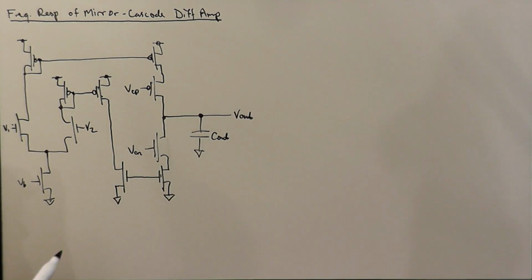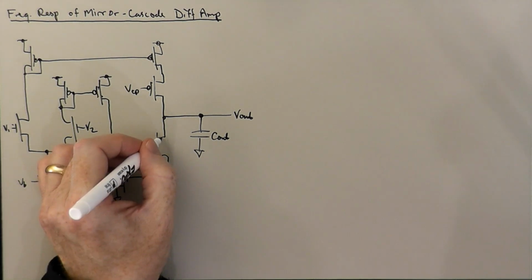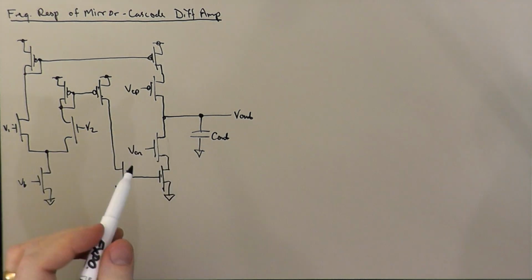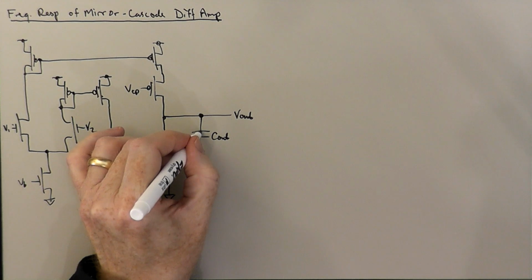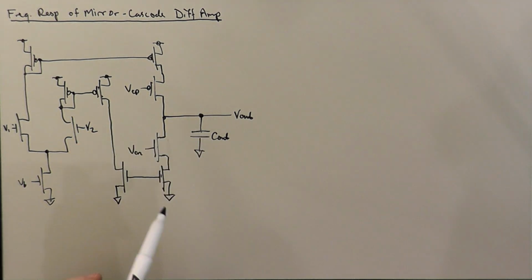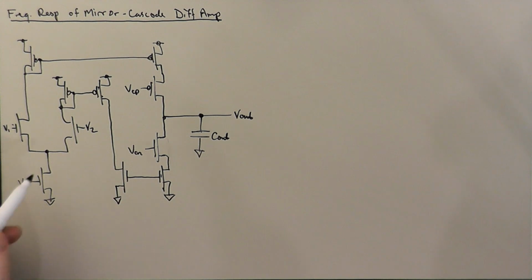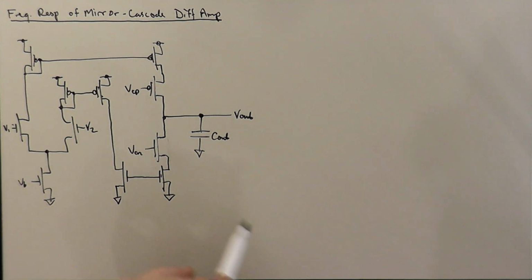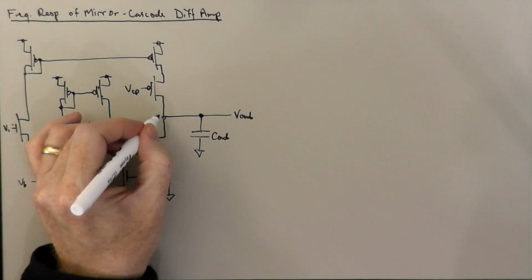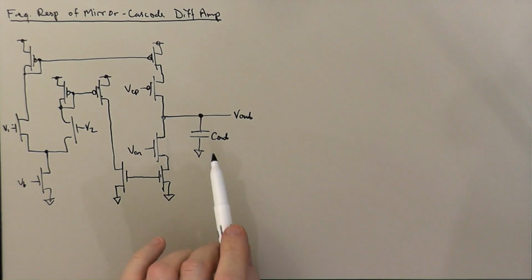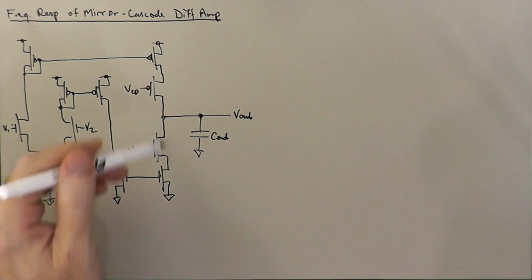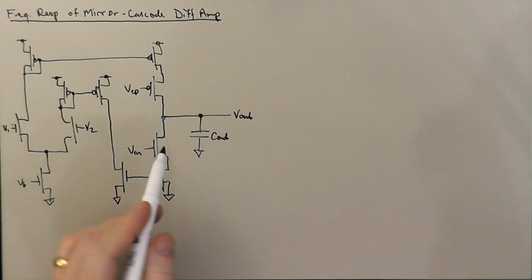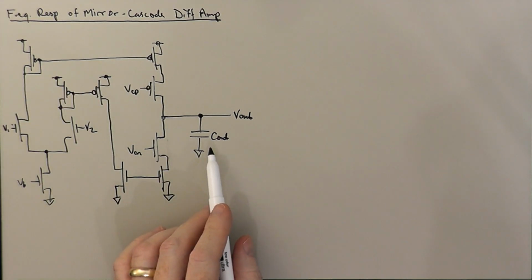And if you take what we did last time and you apply to it the same kind of ideas that we developed with the current mirror amplifier when we put the capacitor on the output node, what we would find is that the GM of the circuit is exactly as it was before when we hold the output voltage fixed. And then the R out, or the Z out of the circuit, would be the Z out of the cascoded output branch, like we had before, in parallel with 1 over j omega C out.